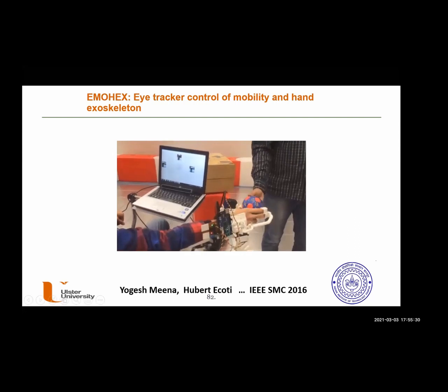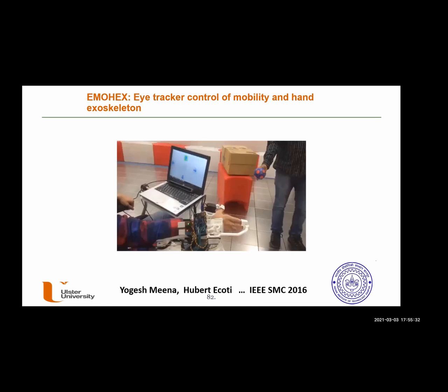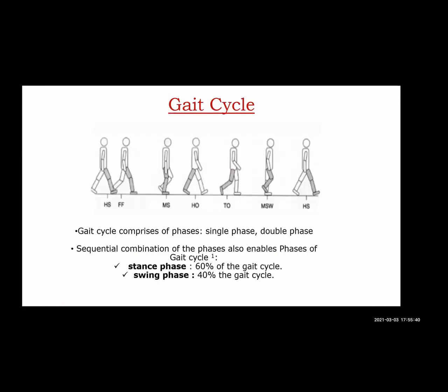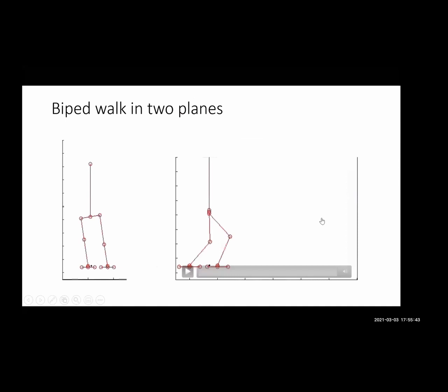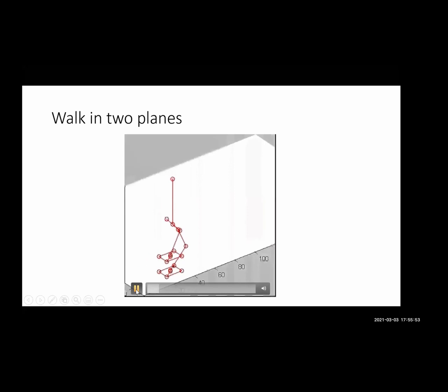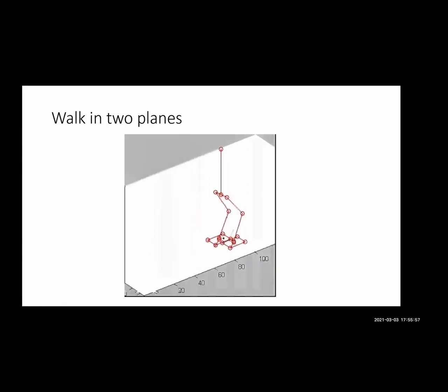So this is basically about hand exoskeletons, and unfortunately, I will not be able to go into leg exoskeletons, but I'll just very briefly give you some idea that in leg exoskeletons also, we try to follow similar principles. That is, you look at the joints, and human joints have this instantaneous center of rotation problem. So for a walking leg exoskeleton, if you're trying to replicate the walking motion, again, you cannot put revolute joints.